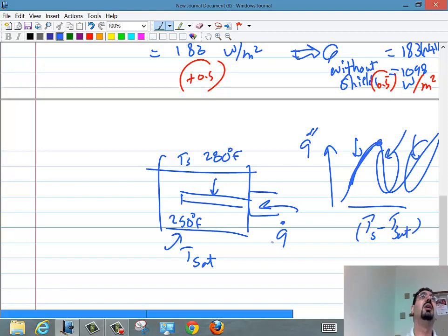Until its radiation and its natural convection at this high temperature are enough to send away that Q. Unfortunately, that could happen at a very high temperature, which will melt everything around the rods, and therefore there is no mechanism to bring any more fresh air or seawater to cool it, or any more safety rods to come in and try to kill the radiation. So the Q controls the TS, and not just like in those problems where I give you the TS.